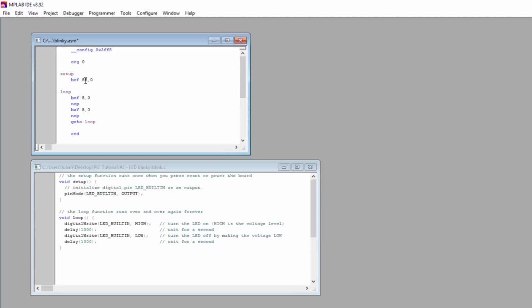That could very easily be interpreted as decimal 85, and of course it mustn't be decimal 85, it must be hexadecimal 85. So I need to type in 0x to ensure that the assembler knows that this is a hexadecimal number. Doesn't matter with these low numbers because they're the same in either number base, but this one's very important.